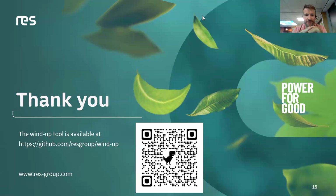Thanks a lot for the presentation. It's very nice. A couple of points interest me. Firstly, on the directional detrending, you talked about times when a certain turbine is offline and measuring the difference there. Is there a risk that in your reference period, you don't have enough data points to determine that difference? Ultimately there's a whole matrix of turbine relationships there. If there's not enough data in the reference period covering a certain turbine being shut down, but then that occurs in the test period, is that a bit of a risk?